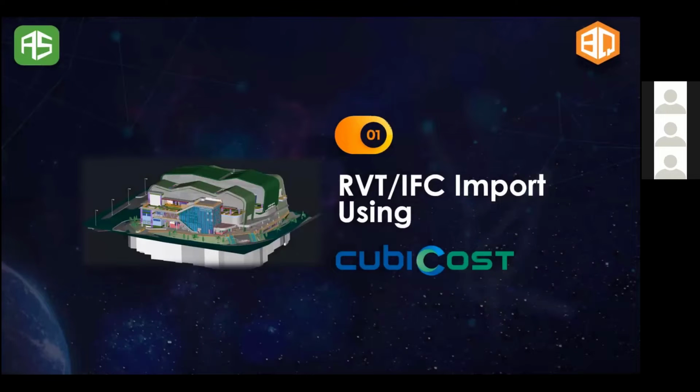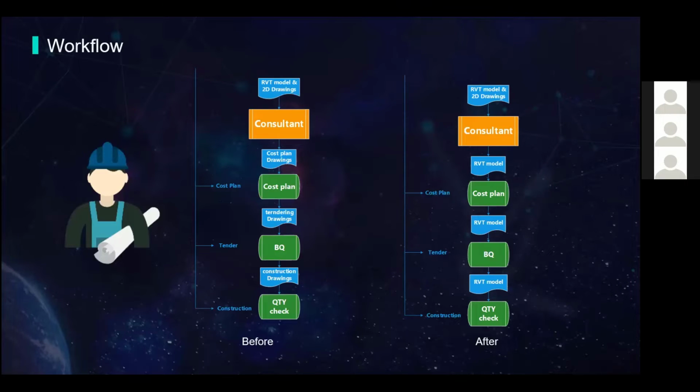So let's look at the normal workflow of Revit to conclude. If you are a design consultant using Revit, you can prepare your cost plans using QB cost. You have to import the model and 2D drawings into your QB cost software, and then you can produce your cost plan. After that, you can start doing the tendering drawings, and with the tendering drawings, you prepare your BOQ. Then you can go ahead with construction drawings and quantity check.